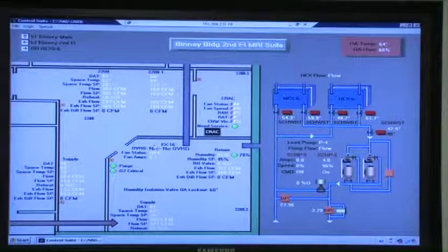Okay. How, with you telling me that, show me here what changes. How does this change during that? When that goes off, what do I see? All you're going to see is the fan status come on, and you'll see amperage on the amps. The dampers are electrically driven. There's no interaction as far as us with the dampers. It's all hardwired circuit, there's no automation interface to them at all. They're interfaced with the fan. Even if you were to walk up to the fan and put it in hand at the starter, it's going to position the dampers and start it.